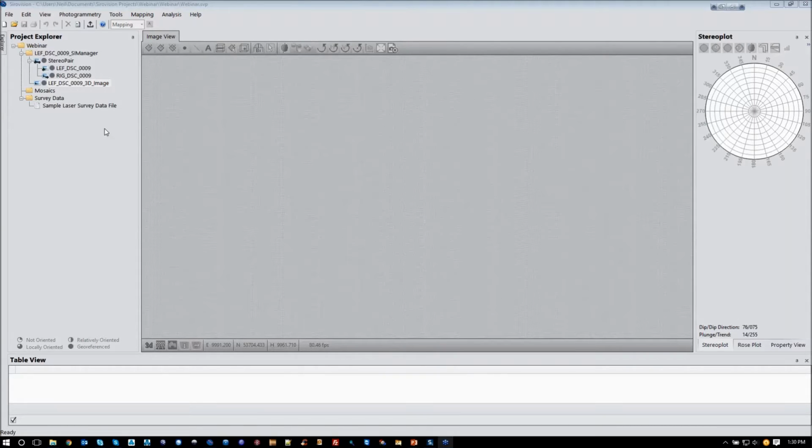Absolutely. So the methodology I was showing today, just for time saving, is just referencing one image. There's a couple of ways you can do it. You can create a mosaic and then georeference the mosaic, or you can take one image, georeference it, and then when you create a mosaic from it, it will actually georeference the images associated with it. Usually, one georeferenced image can georeference accurately 3 images on either side. So you're looking at about 1 georeferenced image for every 7 images.